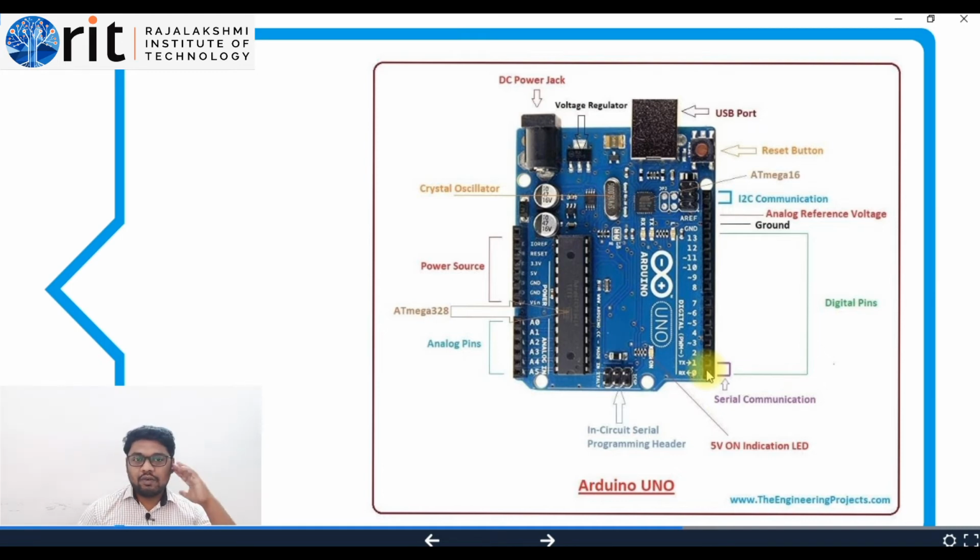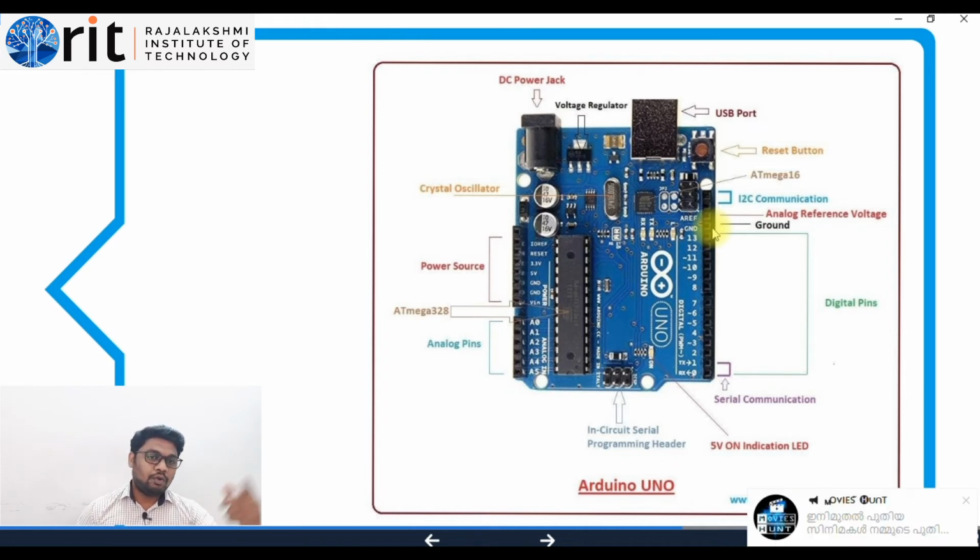Just like your mouth and ears, the mouth is your transmitter and the ear is your receiver. These two pins are used for transmitter applications like Bluetooth, Wi-Fi or Zigbee interfaced with your Arduino board. From 2 onwards up to 13 you can use them for general input purposes. And one more ground is available after the 13th pin, which you can still use.